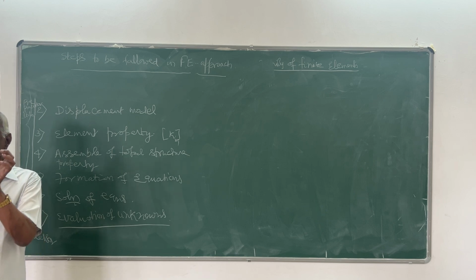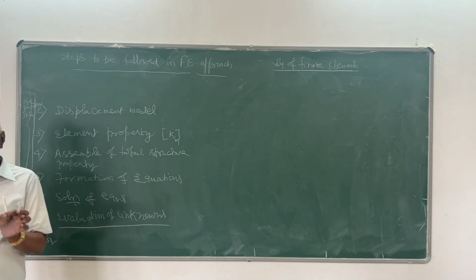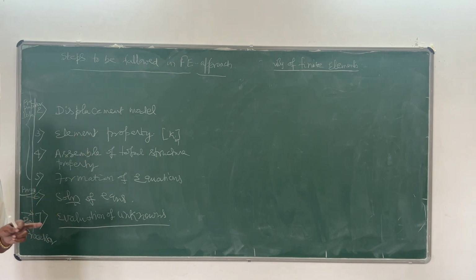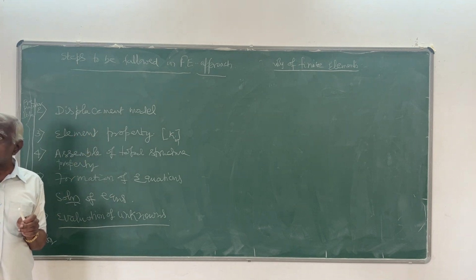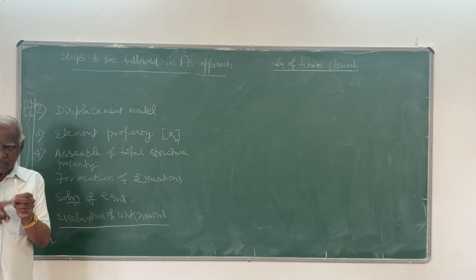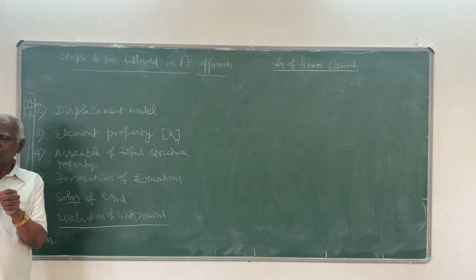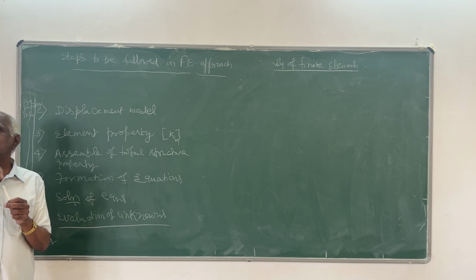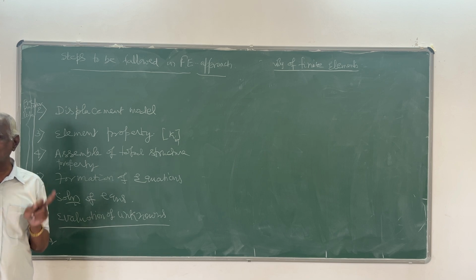For any node of a truss, we have two unknown displacements, and we have to write the model equation. In the case of a space truss, it is also one-dimensional, but whatever the displacement or force, it will have components in three directions, x, y, z. In plane trusses, it is only two.